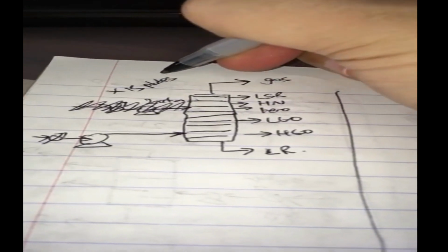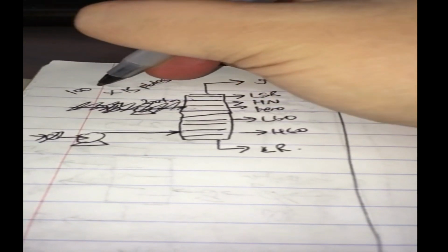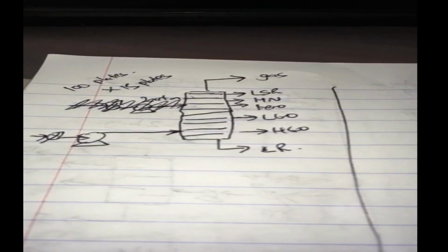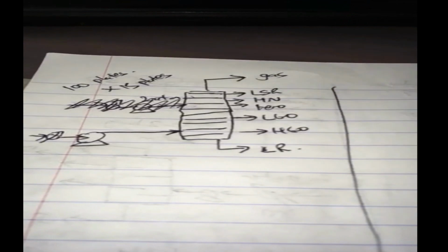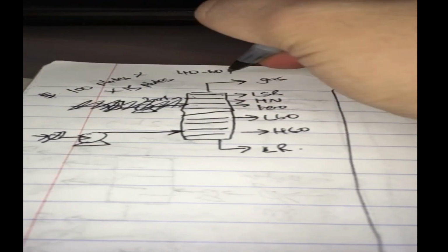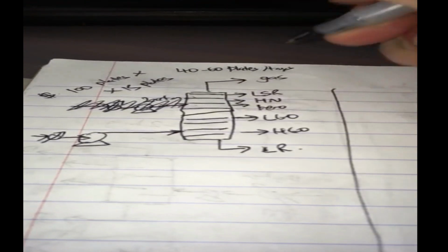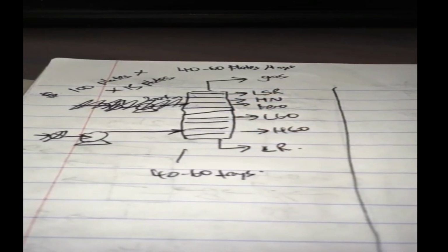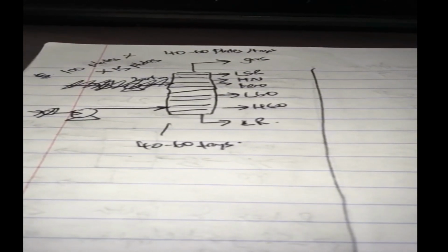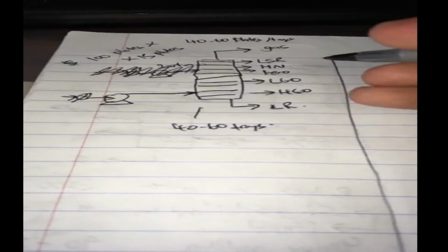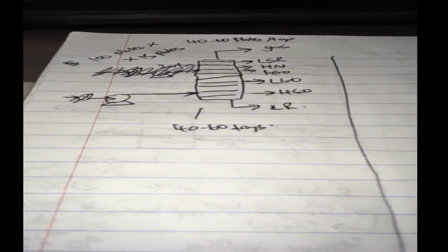So you can't use 15 plates. It's too poor. The ideal of 100 plates, well, that may be okay, but still, the more plates you have, the longer tower you will need to construct. And that's going to be very expensive. So not a good idea. Somewhere in the middle, maybe 40 to 60 trays will be good. So this is about 40 to 60 trays. And so you have 40 to 60 trays, and we have decent separation.